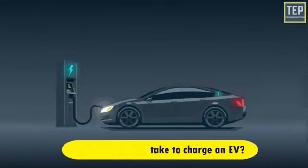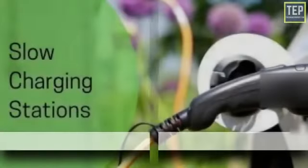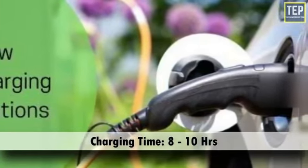There are 3 electric vehicle charging speeds. Slow charging. It is typically rated up to 3 kilowatts. Often used to charge overnight or at the workplace. Charging time takes up to 8 to 10 hours.